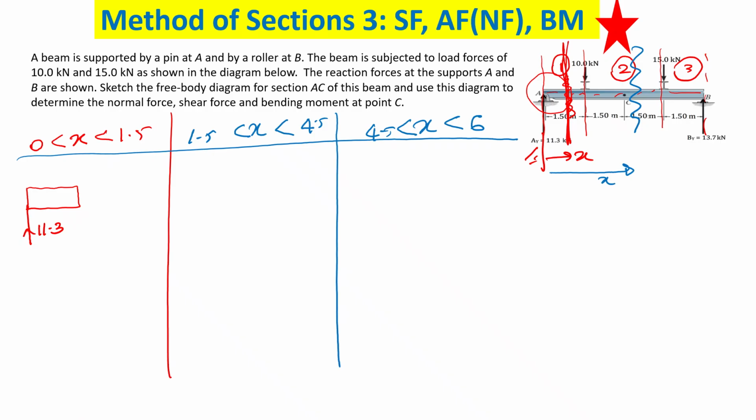Now when we separate, there are actions and reactions. If I say the other part of the beam is like this, I have all the other forces and everything here. So when I separate the beam, I have actions and reactions. So this is the axial force, action and reaction. You need to consider this. We always put it in a way that it will pull the two sides. You can see this side also pulling, this side also pulling. Make sense?